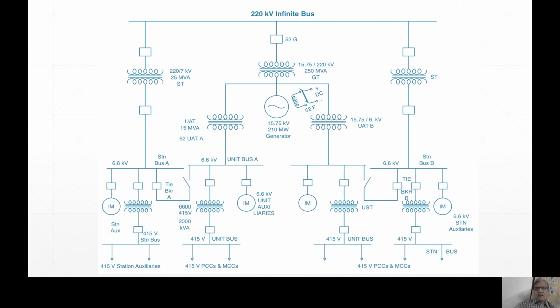It's like a face powder. Because you see, then only it will burn fully. We have to use the complete energy of coal, the potential energy of coal. And coal can burn in the presence of oxygen. So you have to feed oxygen and therefore you have to run the primary air fan. You see all these things. The primary air fan is a 1250 kW induction motor. It is a 6.6 kV motor. It's a large motor.